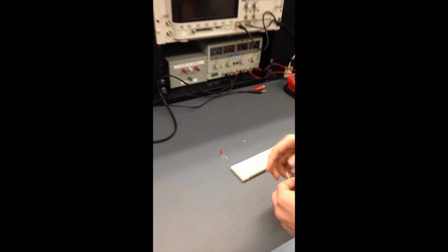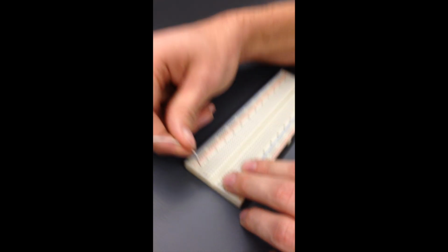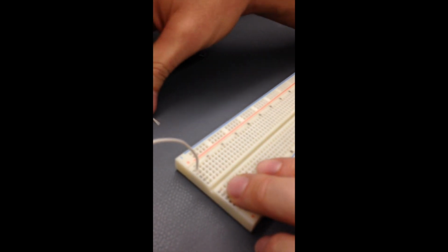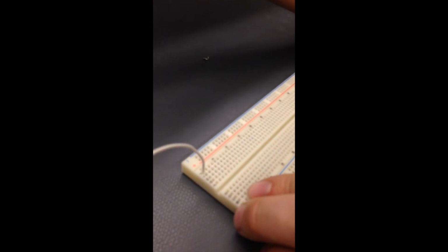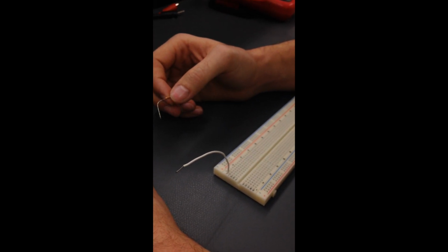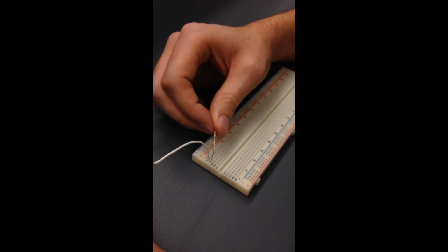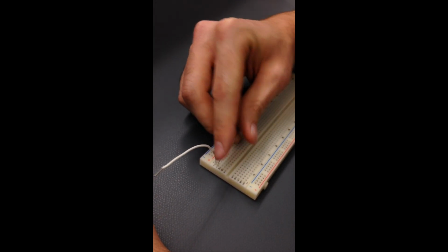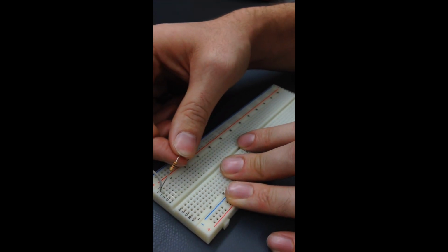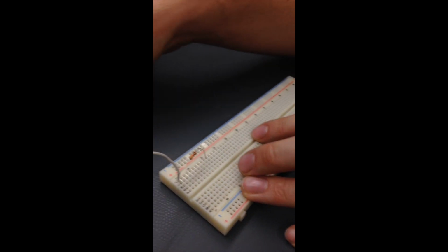First, going back to the breadboard, we will put one end of the switch in a port on the breadboard, then connect the 1 kilo ohm resistor by putting one end into the first row, connecting it to the first switch, and then with the other end put it in another row like so.